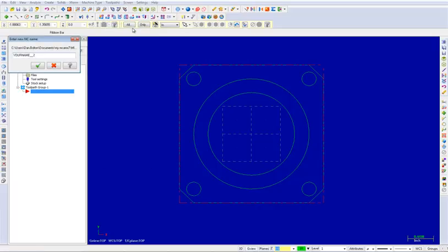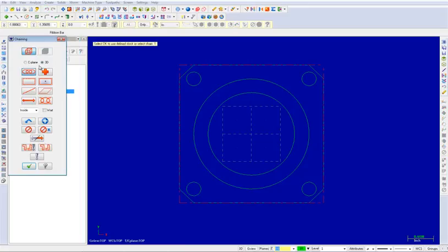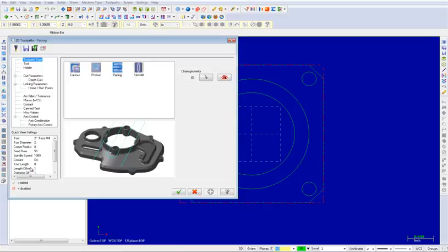If a prompt appears, enter new NC name, select the OK button to accept the default. When the chaining dialog box appears, choose the OK button to use Define Stock and exit the chaining dialog box. You should note that Mastercam will create the facing toolpath defined from the stock setup. In the toolpath page, you will notice that the facing icon is automatically selected.